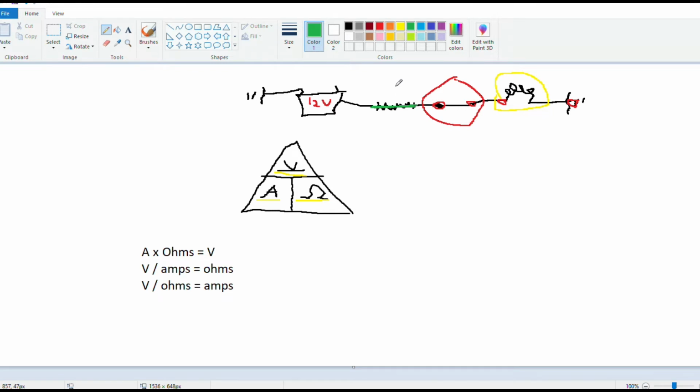A very good point was brought up to me while I was reviewing this document, and I wasn't entirely clear. When I say green wire, I'm referring to the color of bronze wire changes after it's been exposed to moisture, and that color is green. So when I say green wire, I'm not referring to a physical green wire. I'm referring to corrosion that has happened inside a wire that has turned the color green. I just needed to clarify that, as there could be some confusion there.